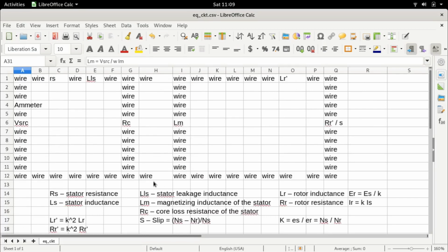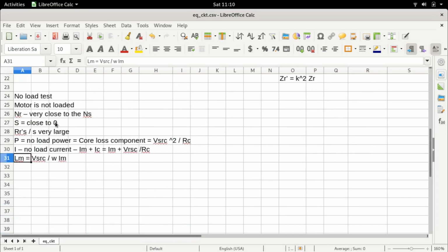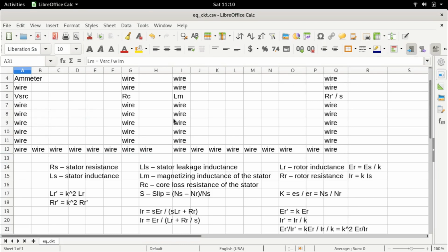Now, of course, in the simulation, we do not have a no-load test. So if I were to calculate this, I will assume certain core losses and a certain magnetizing current. These are assumptions we make in order to estimate our parameters. But again, these assumptions are actually quite reasonable because usually most machines are fabricated to such specifications. This will come very soon, in the next few lectures, when we start actually programming this induction motor model.